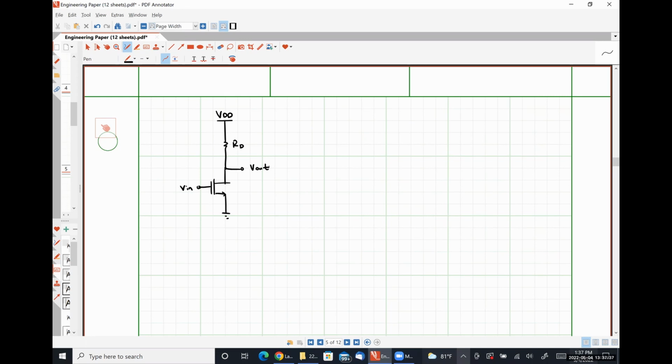Okay. Our input signal is our gate source voltage. We are controlling our small signal drain current, ID, and we're measuring that small signal drain current by this output voltage, which is just negative ID times RD, right? So our open loop gain in this system is simply negative GM.